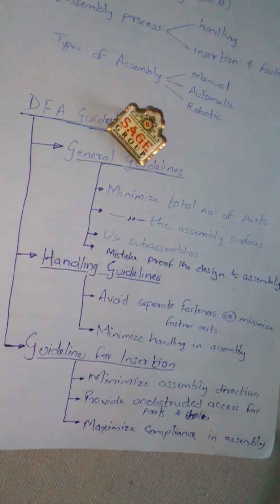Excessive assembly force may be required when the parts are not identical or perfectly made. Allowance for this should be made in the product design. Designed-in compliance features include the use of generous tapers, chamfers, and radii. If possible, one of the components of the product can be designed as the part to which other parts are added and as the assembly fixture. This may require design features that are not needed for the product function.